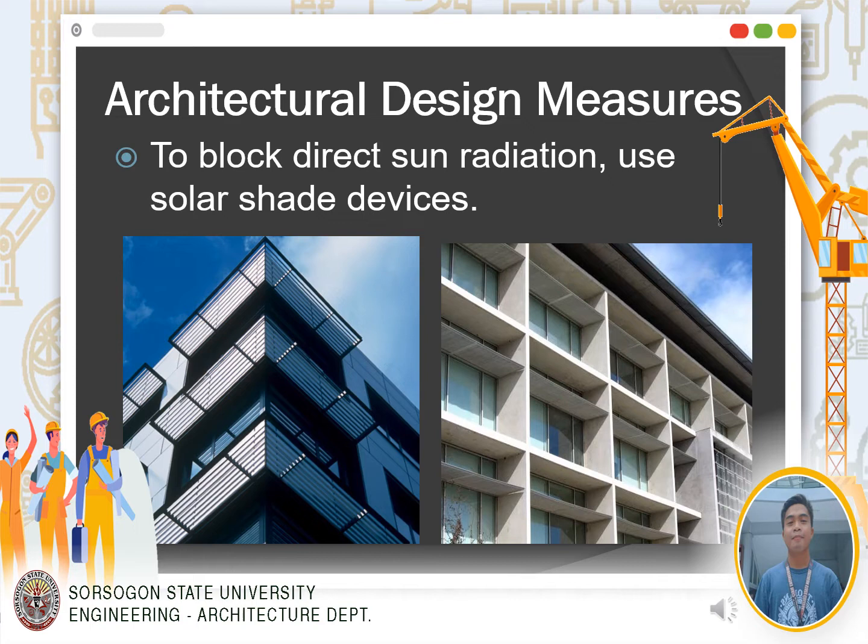Shading devices can be classified into two main categories: fixed and mobile devices. Fixed devices include overhangs, horizontal or vertical louvers, and egg crates. Mobile devices, operated manually or by automated systems, control sunlight based on adaptation to solar radiation, indoor temperature, or illumination level.